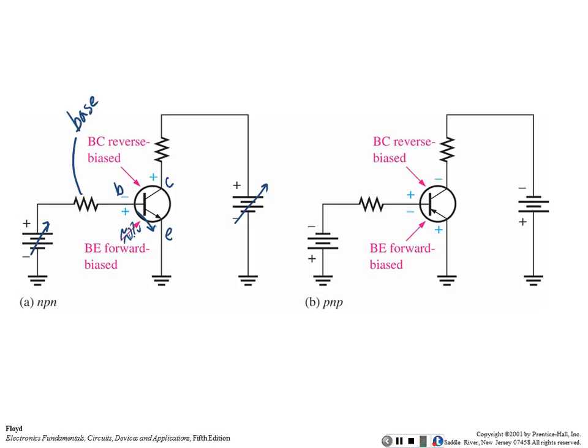And then, of course, what would happen is I would come up here, and let's say I put 3 volts right there. Now, what's going to be dropped across this resistor right here, if it's a silicon transistor? 0.7 is being dropped across the base emitter, and Kirchhoff's voltage law says the sums of the voltages in a loop have to be dropped.